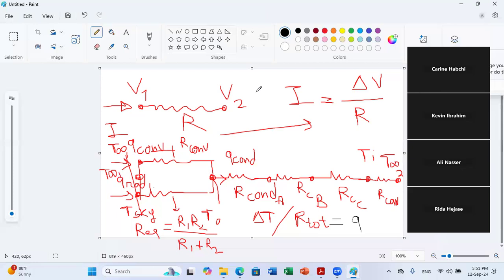Sometimes windows can play a positive role. We want heat to be transferred to the inner environment, for example during winter, when we need to benefit from sunny hours to heat our space. This is why we need to optimize the orientation of the building to absorb more sun during winter and less energy from the sun during summer.